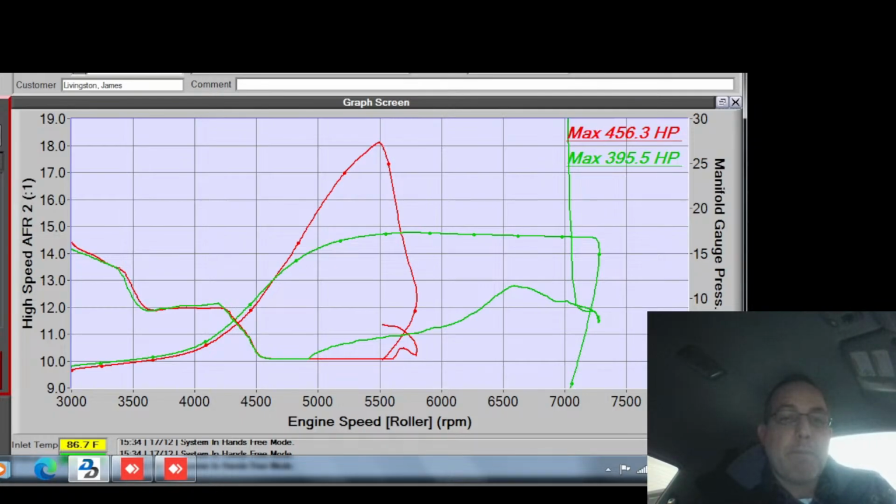Still too much tip-in. But it's too much tip-in at the larger throttle movements, not at the small throttle movements. So I can try and change it. I'll make a huge change right now and see what happens, see if it falls on its face or what. Huge change.